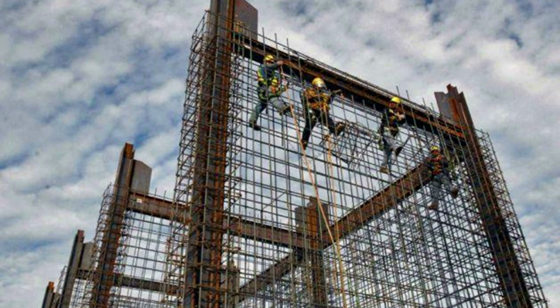Meanwhile, Arrangement 3 and Arrangement 4 can be considered fair arrangements. However, Arrangement 5 and Arrangement 6 show some of the poor arrangements for the shear walls. Shear walls, in high-rise construction, can be conveniently used around the cores for enclosing the building services. This figure shows an example of shear wall construction for steel frame structure.